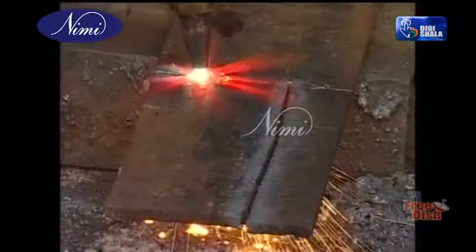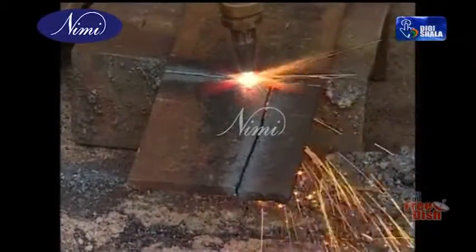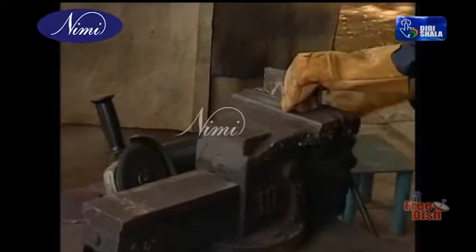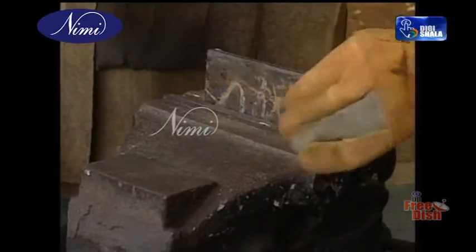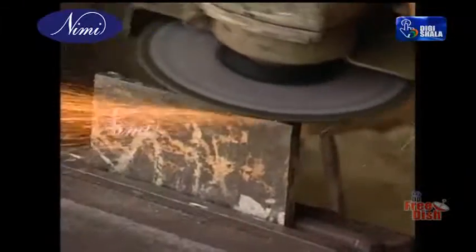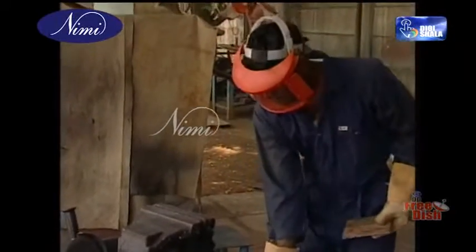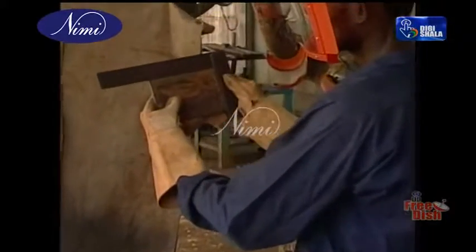Similarly, the positions of the work pieces are changed and the remaining sides of the pieces are cut. Now the cut pieces are held in the vise and the edges of the specimen are ground square using a grinding machine. The perpendicularity of the specimen is checked using a tri-square for the orientation of the joints. Now the plate is ready for the fit-up.